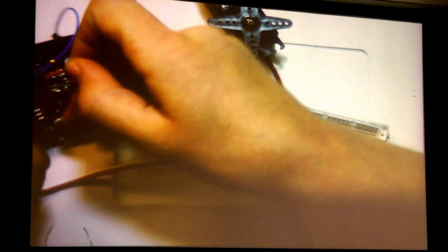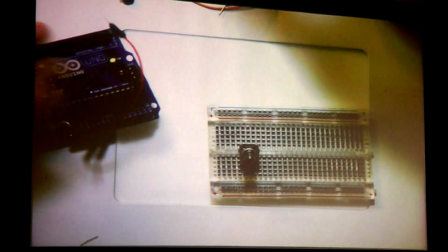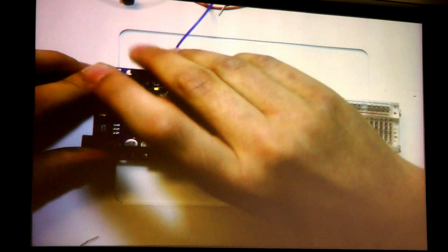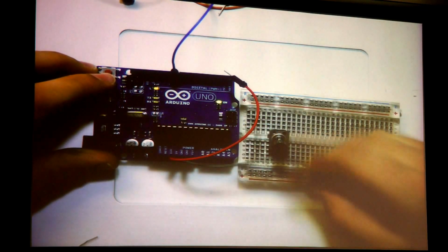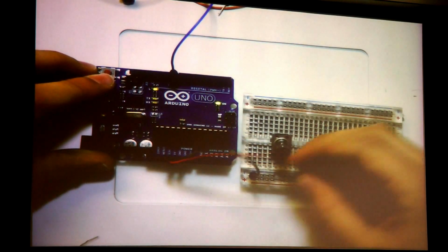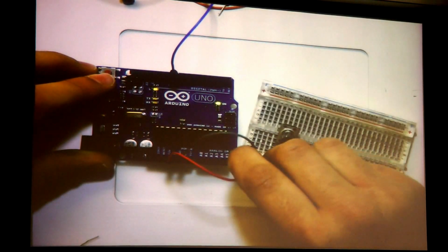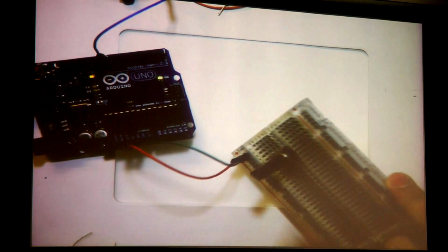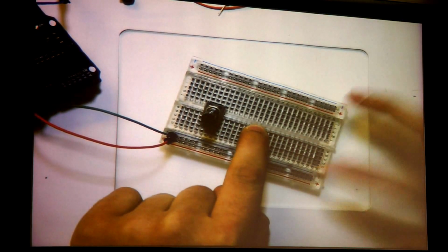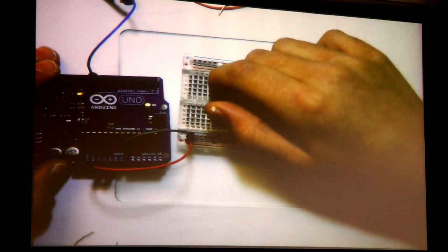So what we'll do is, this is where we could use our power rails on our breadboard. We'll hook up power and ground from the Arduino. Let's see how I can fit this on here. Hook them up to the power rails. So we'll hook up negative here. If you mix them up, bad stuff happens. And we'll hook up positive to here. So the power rails are only connected on this side of the breadboard, not this side, so you could add jumper wires. I'm not going to because I don't really need to.